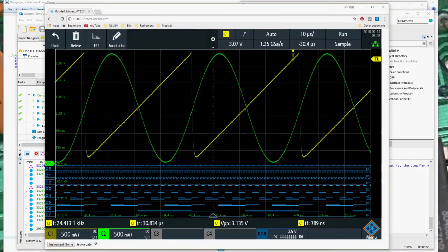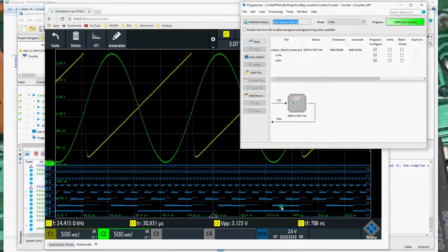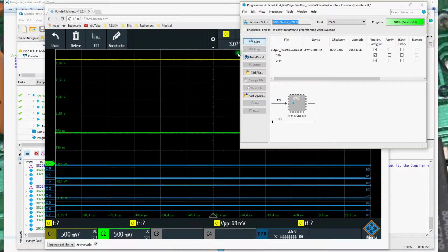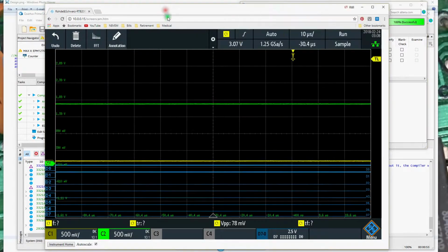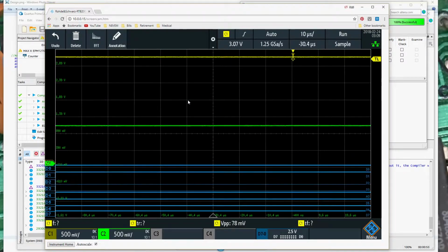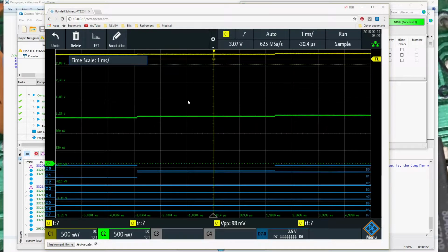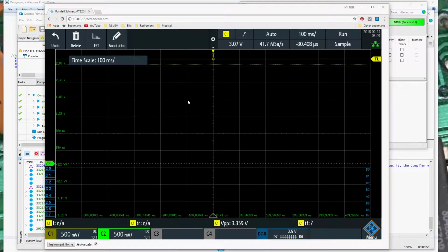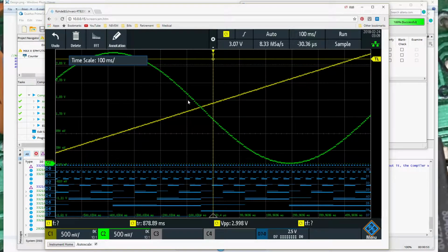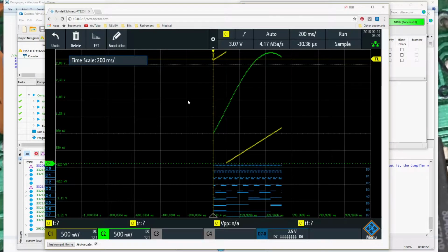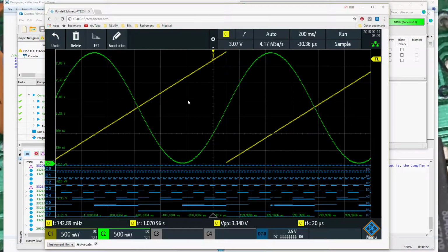And let's bring back the oscilloscope display and the programmer, and we'll go ahead and download that. Again, the board shuts down while it's being programmed. And we're now on the slowest possible signal generation, so let's slow the scope way down here. We're at 10 milliseconds per division, 100 milliseconds per division. I'll do a single capture here in a second.